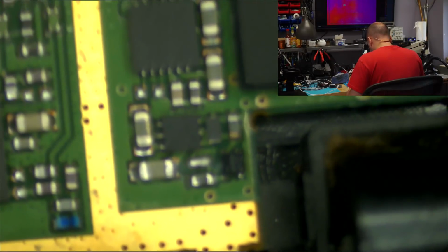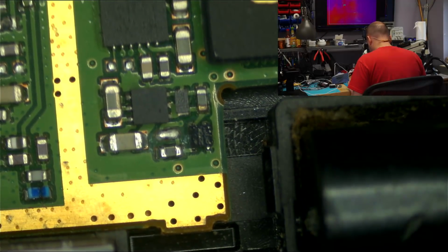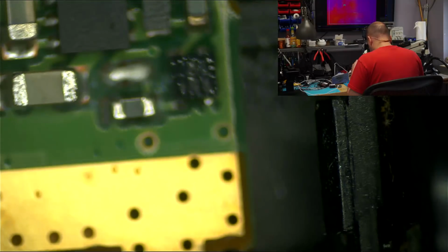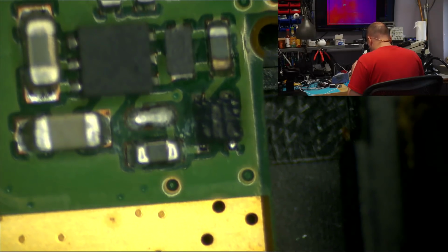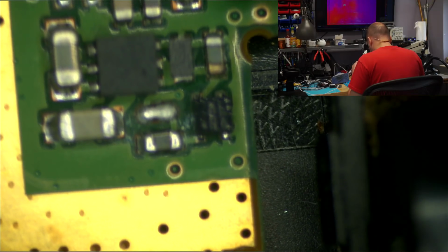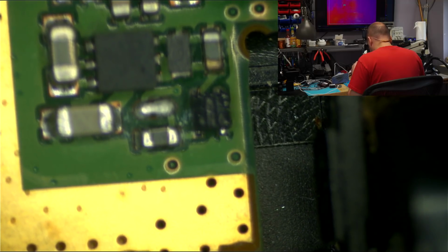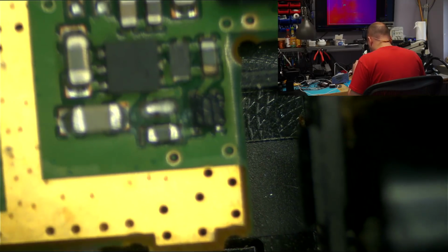Okay, let's look at the other corner here where I saw a short too. Oh, look at that. Could that be some corrosion right here? This is a liquid damage phone, and I see some corrosion right here. Is that corrosion or just... yeah, that is corrosion. I thought that it was just some scraping off of the PCB. And I think to be safe, I'm just going to windshield wiper this whole little corner and just replace everything. We do have 2 known workings, so...